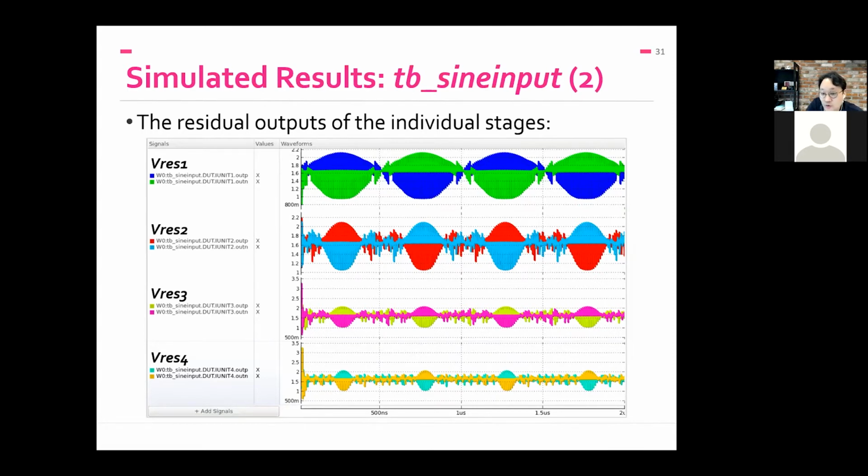So in order to take this into your UVM environment, all you have to do is take this model and run it, and supply some additional options, like including our primitive modules as one of your module lists. And there is an additional shared library used by the XModel primitives. That's it. That's the goal of XModel, do everything in SystemVerilog.